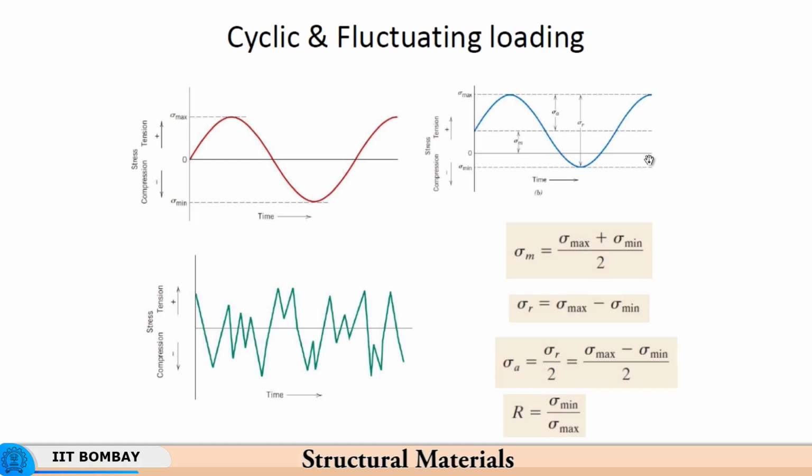Now, this is the typical undefined or unpredictable cycle. There is no pattern as such in this. This is the typical cycle characterized by a chair or furniture being placed at various locations. If a person sits and gets up, sits, gets up, there is no reason why the stress should go into compression. So the cycle will have to end at 0 here.